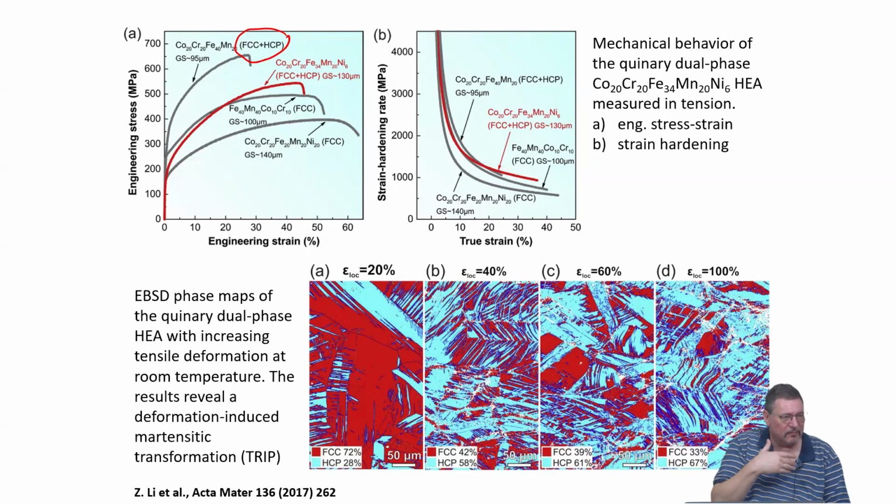And it's basically, when we think of how twins originate, this is coming from the stacking fault, right? So you create the first stacking fault, and then when the second stacking fault goes along the same plane direction, but a parallel plane, then you basically have a twin, a mechanical twin. And this is how twinning-induced plasticity works.